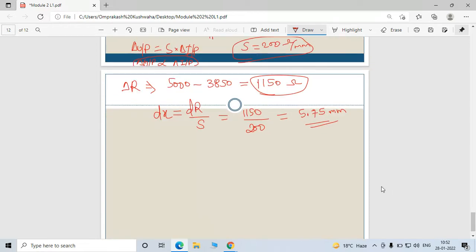So this is displacement, change in displacement. Now second case, this is for first case. For second case, same way, what are the changing resistances? Irrespective of sign, you can use this, find out these changing resistances. What are the bigger quantities? 7560, right, which is given to you, and your output is 5000 ohm. So what is the changing resistance here? It is 2560 ohm. These are the dR.